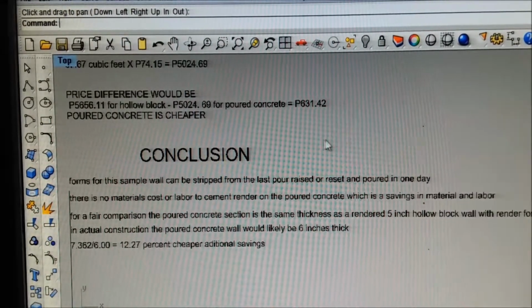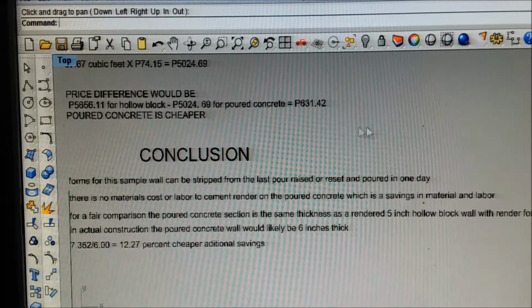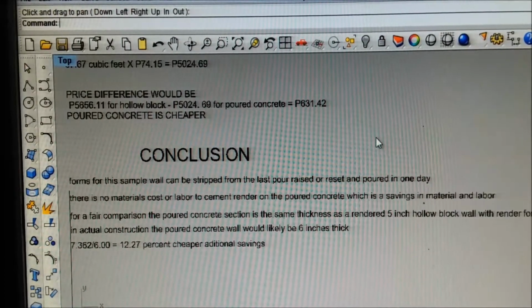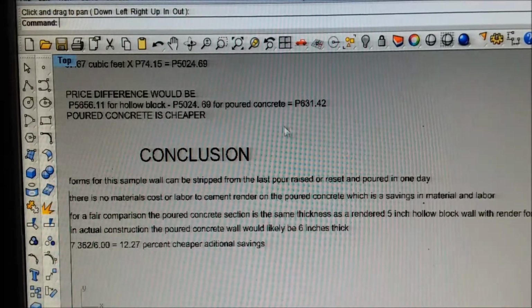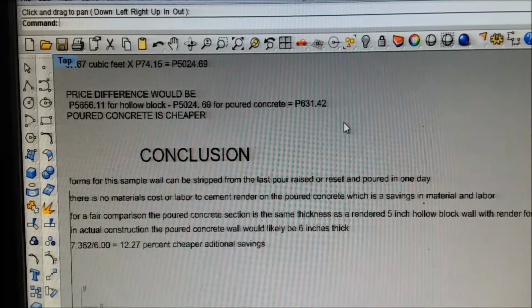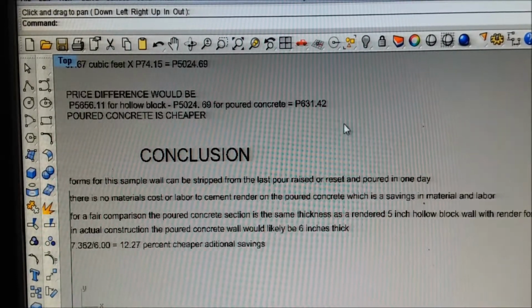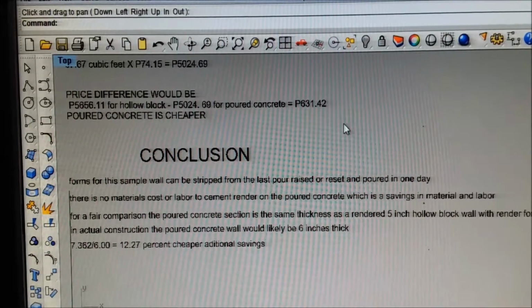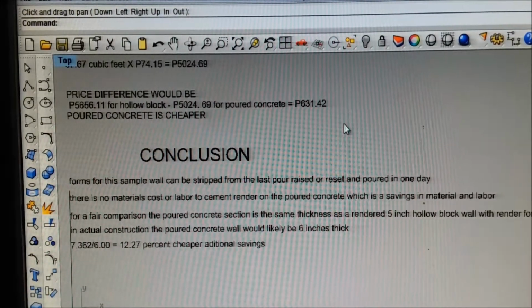But we're trying to show somebody how they can reduce the price of building a house in the Philippines. And also the hollow blocks, apparently, if they pass a 500 PSI test, they're sellable. I think the code likes you to have 860 PSI, pounds per square inch, of support value on a hollow block. They don't generally make that.